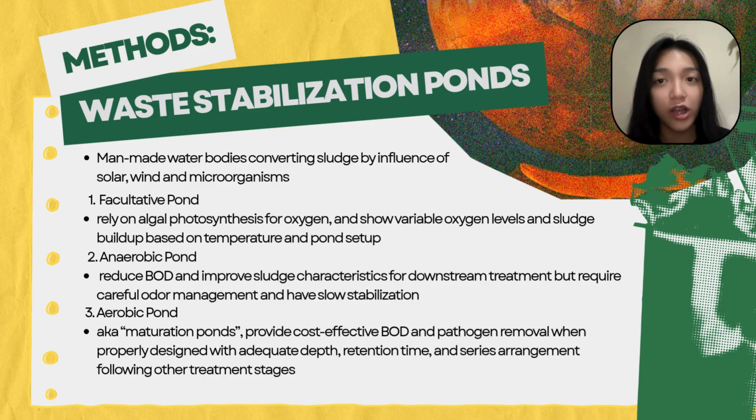Aerobic ponds use oxygen, sometimes with mechanical aerators, to maximize the breakdown of organic matter and reduce harmful bacteria. Maturation ponds are a type of aerobic pond designed to polish the water, ensuring safe, high quality effluent.